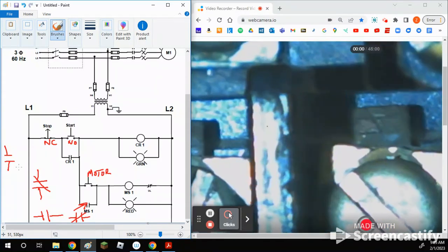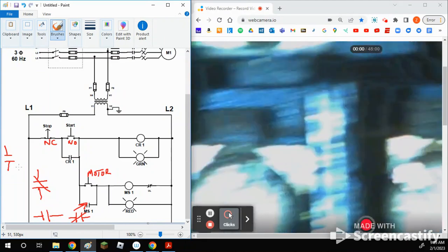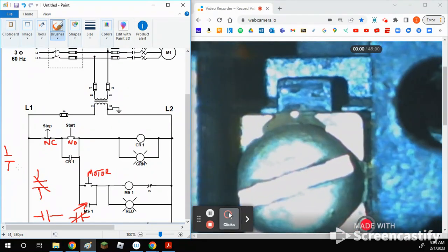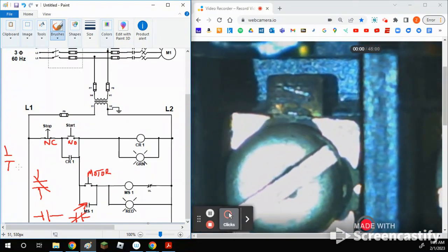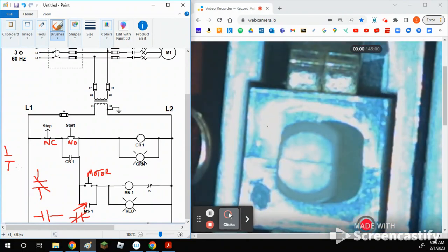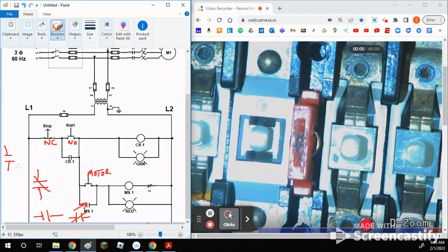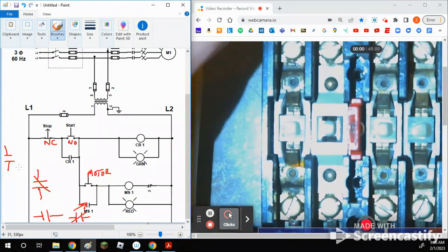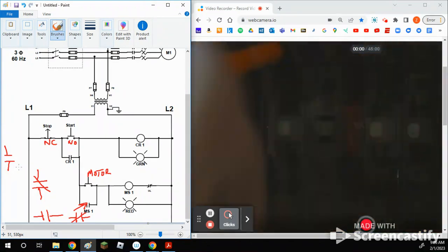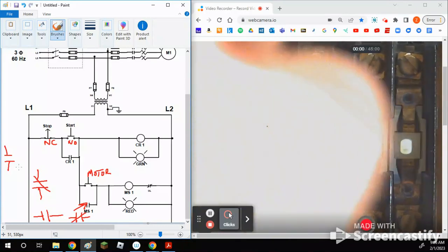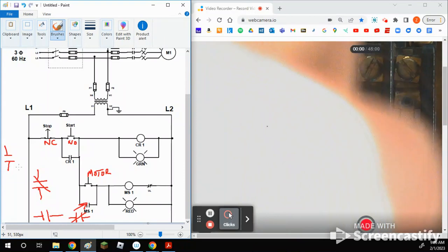So that, where are you at? That one is normally closed. Normally closed. Normally open. Normally closed. Let's see if the back sides of these things are any clearer. To change these out, if I wanted to make, let's say this far one on the left, normally open, take those two screws out. And just flip it around.